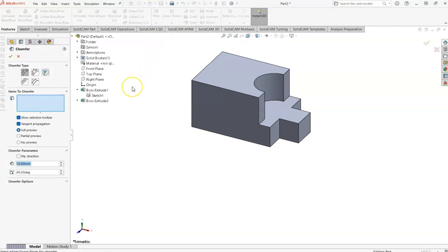Okay. Now there's a lot of different ways that you can chamfer. In this case, we don't have any type of measurements in degrees. So we don't have any angles. So you can see these little symbols. It shows angle, A, and D for distance. So angle and distance. What we have is two different distances.